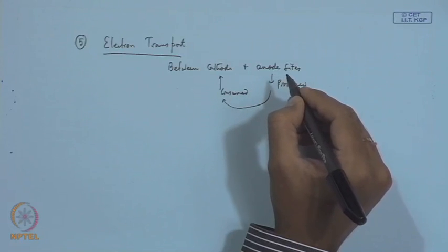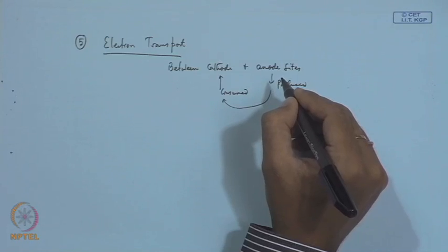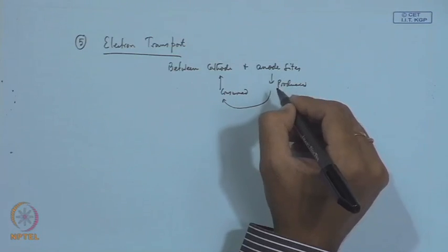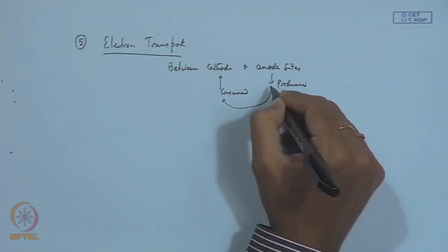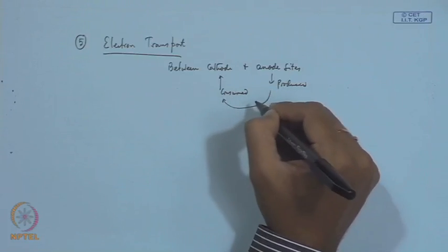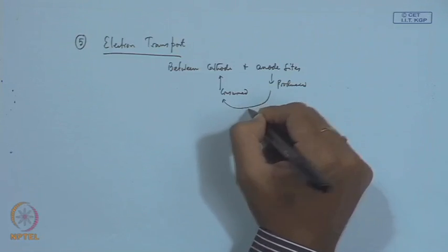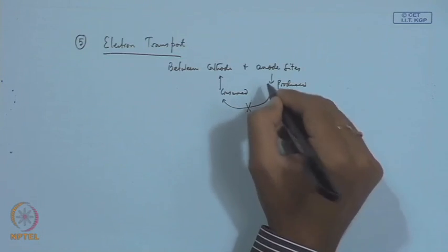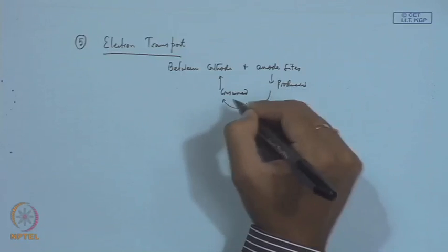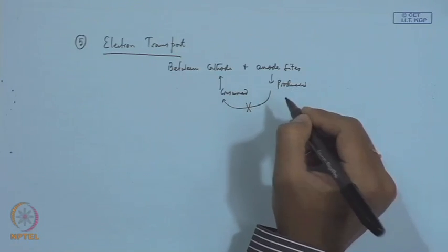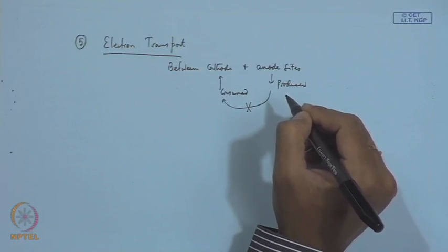Okay. Without flow of electrons between anode and cathode, these half cell reactions will not be completed. So, there must be some means, like a wire connection; electrons flow along the wire from anode to cathode could be a way. So, if by some means we can hinder this electron flow from one side to the other, then possibly we can reduce the extent of corrosion.